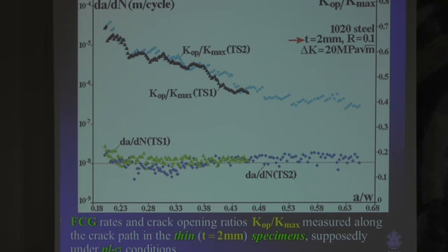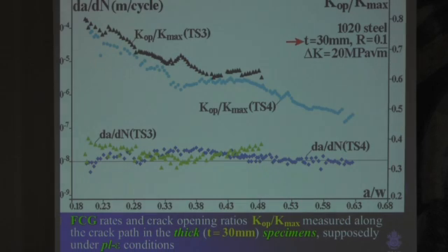We should have different behavior in plane strain, at least that is what we can believe if we believe in Elber's idea. So we took the 30 millimeter thick specimen and did the same test.